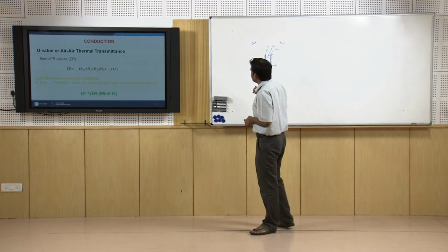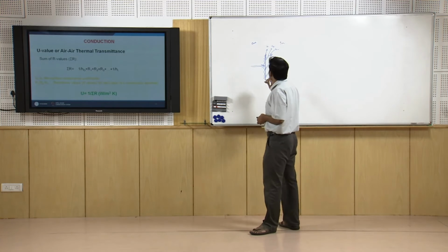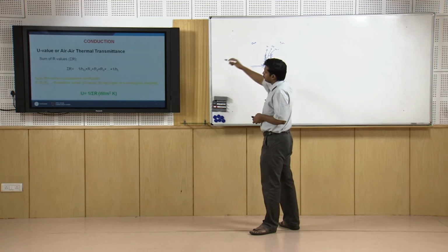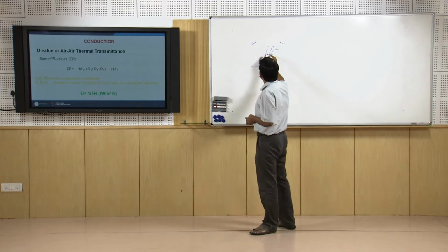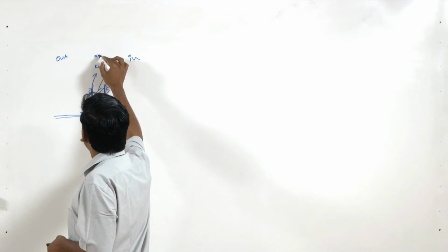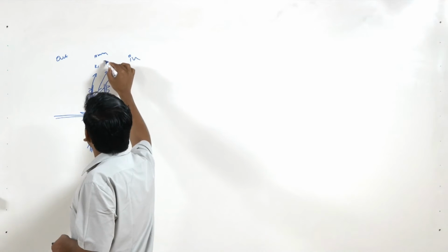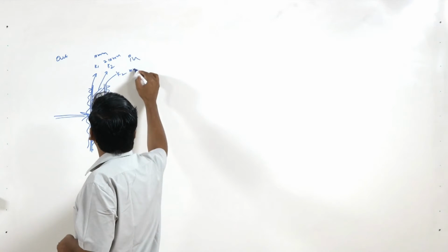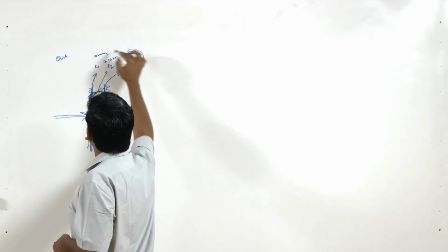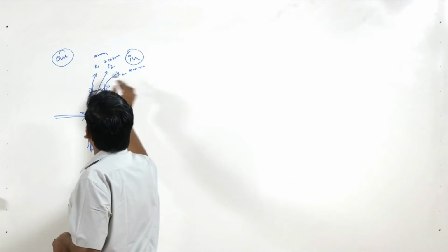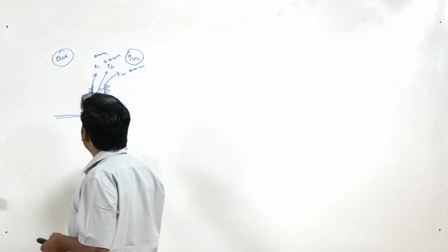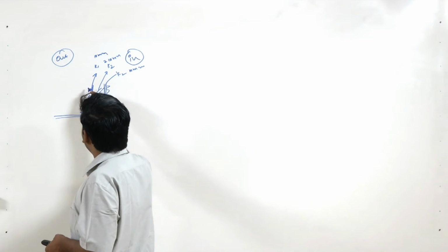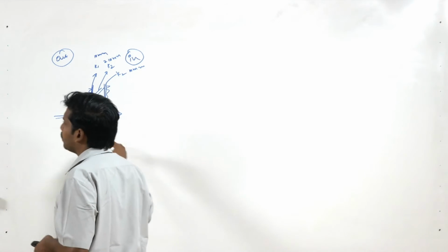We will look at it in more detail, but to quickly understand, there is K1, and if you include the thickness, say now it is 10 mm, this is 210 mm and this is another 10 mm. Together, this gets you a 230 mm brick wall, but apart from this you have a film coefficient out and film coefficient in.